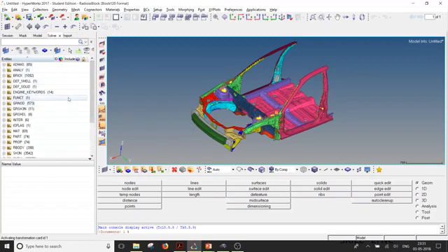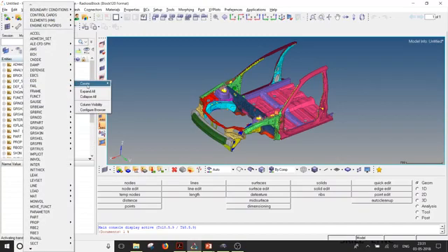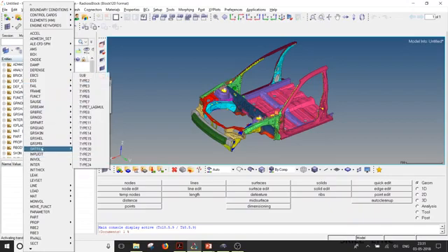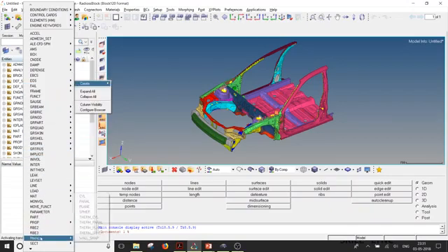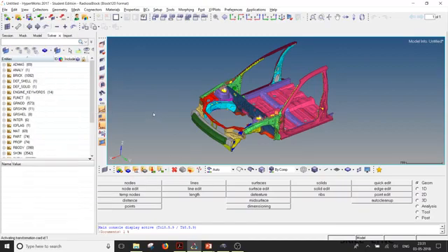If you want to create, let's say, a rigid wall, you can simply right click here and go for RWALL. That is the control card or block card for the rigid wall. Then in that you can select cylindrical or plane or whichever you want. That way you'll have to operate through this and you will get through this easily.